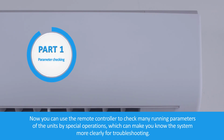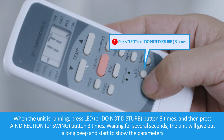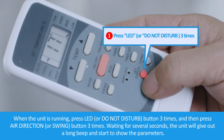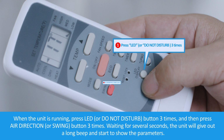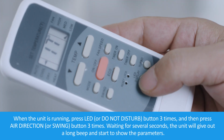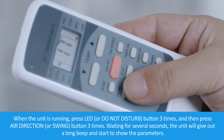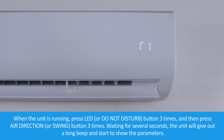Now, you can use the remote controller to check many running parameters of the units by special operations, which can make you know the system more clearly for troubleshooting. When the unit is running, press LED or Do Not Disturb button 3 times, and then press Air Direct or Swing button 3 times. Waiting for several seconds, the unit will give out a long beep and start to show the parameters.